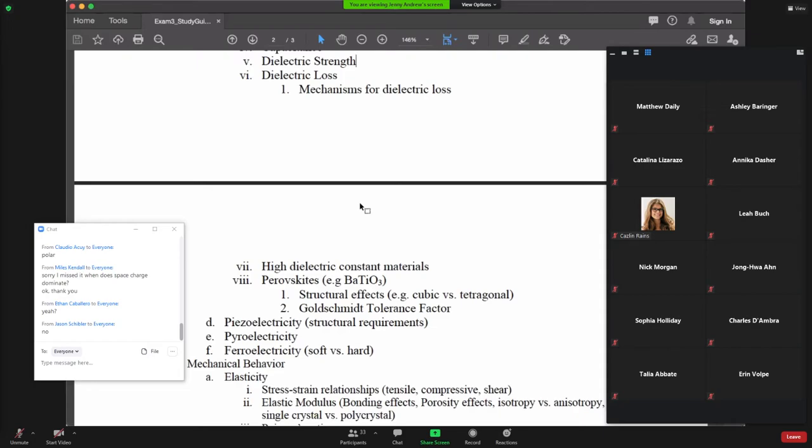And we often see this dielectric loss in terms of a phase lag as we're measuring the properties of these materials. So if you put a dielectric material into an applied electric field, say it's got a sine wave, what you'll find is you have some slight lag in the material responding. And that's just because you have some losses. So the material absorbs some of that energy due to loss before it responds. And the magnitude of that phase lag tells you about the loss. Okay.